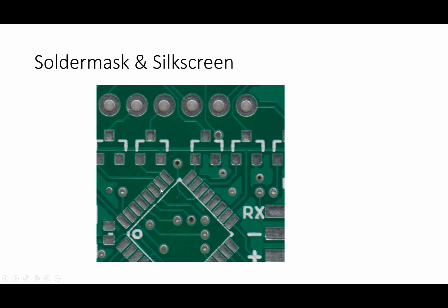In the first lab, you're going to deal mostly with surface mount components in your design, although later on we're going to switch over more to the boards that you're actually going to manufacture, and in those particular cases we'll deal with through-hole components. I did mention here quickly this via. That's something we typically don't solder to. We'll talk a little bit more about that here in a bit.